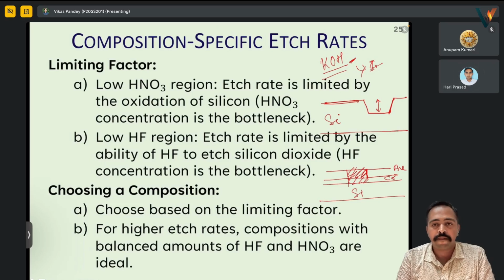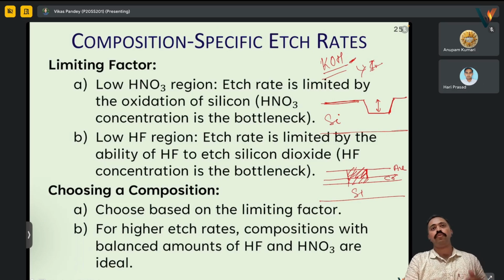So in case of silicon and SiO2, where we have to make patterns, especially MEMS kinds of structures, the depth is relevant and it is measured using a profilometer. But when we are dealing with simple metal layers, where we have to pattern for metallization, we don't need to worry so much about how much thickness of etching has occurred. Yes, we need to know how much thickness is there, because that is how we will determine what time to keep it to etch out properly.